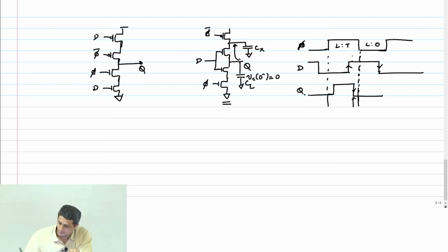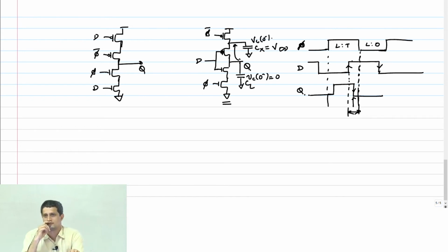Now at this phase, in this period here, my clock PMOS is on, right? And what has happened to D? It has gone high, thereby turning off this guy. So what is the state of Cx? VDD, right? Vc of 0 minus is VDD. So this Q now, because of this, when my data falls in the opaque state, will charge share and come to some in-between value.